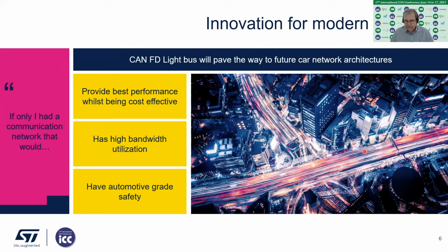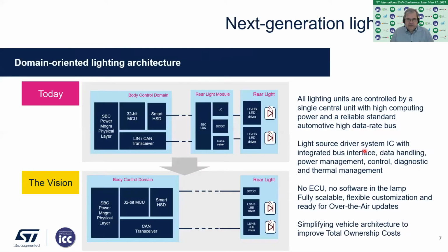And of course, when we think about the rear lights, we do not want to have them turn off. We don't want to have the turn indicators pointing in the wrong direction. So we need a high automotive grade safety for that as well. And therefore we came up with the CAN-FD and invented this kind of CAN-FD light bus at that time. So now look again at the next generation light design.